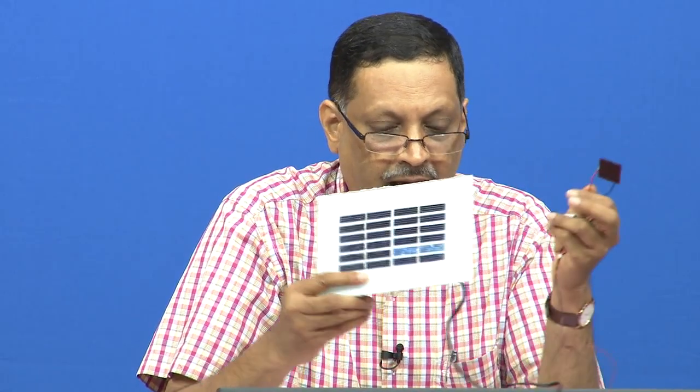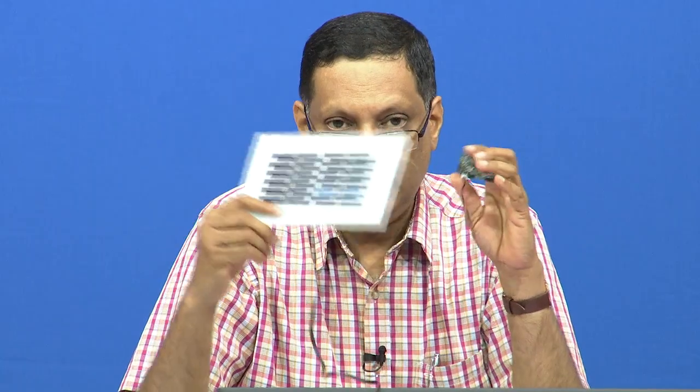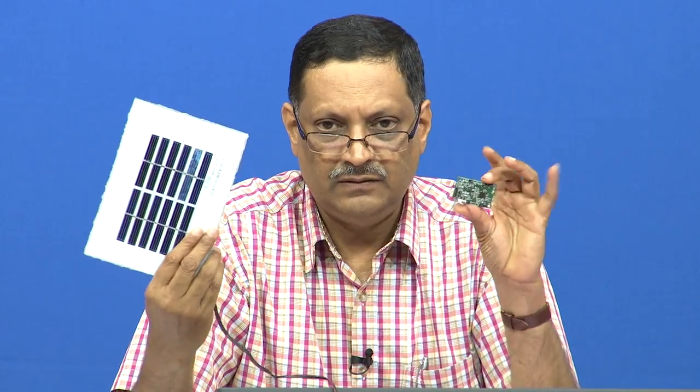I can also tell you that this is a bigger panel which we got from another vendor, and perhaps the right solution would be to interface this panel with this LTC3105. This is a bigger panel. This is a 600 milliwatt panel, and perhaps this should be okay for your application. But you see now the size of this panel is not comparable to the size of the electronics, and you have to really imagine what application it will have before you try to deploy it for indoor applications.